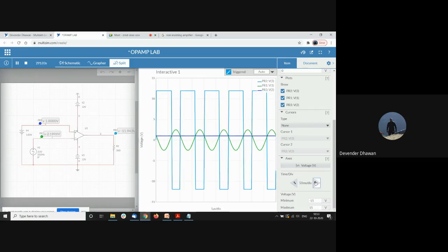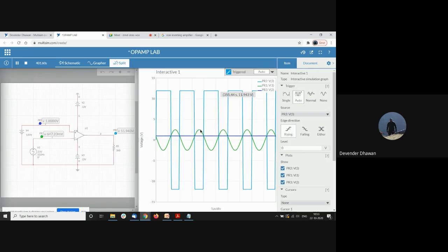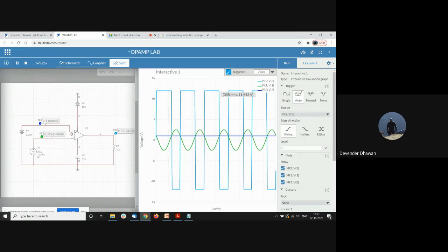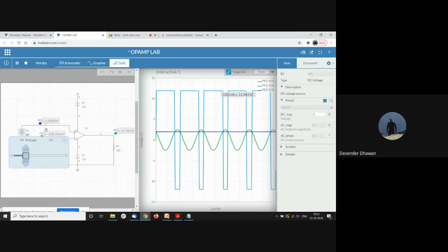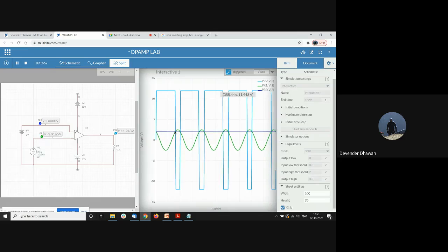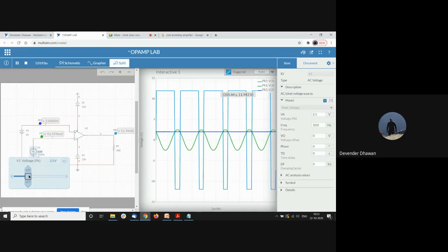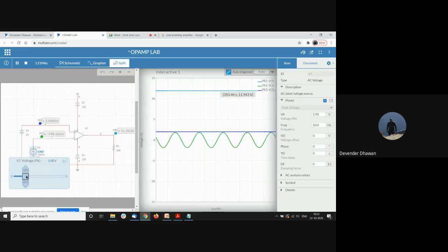As you can see here, as soon as our input voltage is crossing this particular reference voltage, which is set at 1 volt, we are getting a negative peak on our square wave. Otherwise, it is positive. Okay, that is because we are using the inverting end. So if let me just try to shift this to, let's say, 2 volt, and then you see now our negative peak is only for this time period. Okay, so I can just simply move it around and see it change.